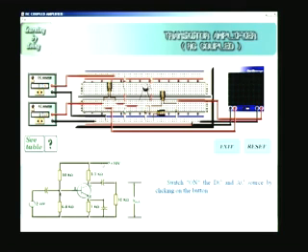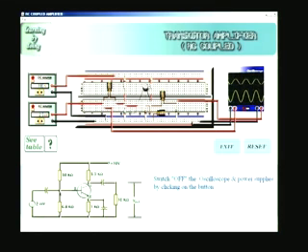So it is exactly the same as the circuit that is drawn here, which is also the circuit which you saw previously. Now let me quickly switch on the oscilloscope. Immediately you can see I have a 10 volt VCC, and I give about a 2 millivolt AC source at about 1 kilohertz frequency. You can see the input signal is very small, the output signal is very large, an amplified signal you get. So it is very easy to construct a simple RC coupled amplifier making use of a simple transistor and a voltage divider bias or whatever. In this case I have given an example using the voltage divider bias.